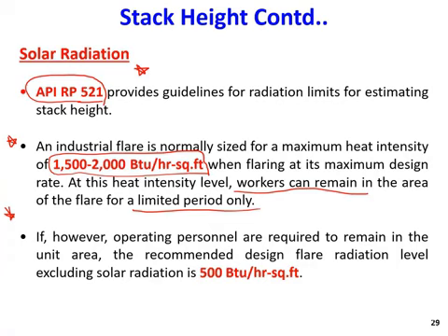However, if the capacity of the flare is much less, let's say about 500 BTU per hour square feet, in that case the radiation is not that severe. So the workers, the operators, can remain in the area permanently, for a longer time.